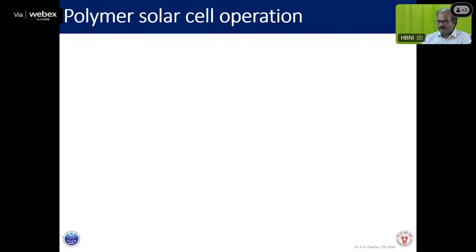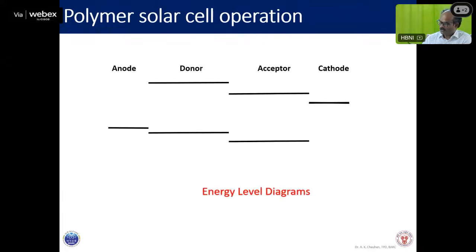So yesterday we saw a typical animation for silicon solar cells. Here you will see a typical organic solar cell and how it works. The first thing is that there we used to call N-type and P-type. Here in the organic, those molecules we call donor and acceptor.